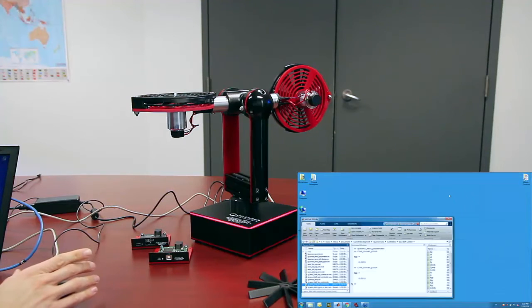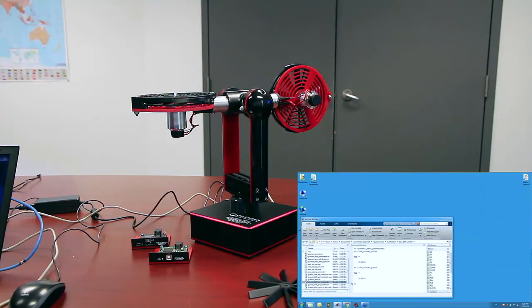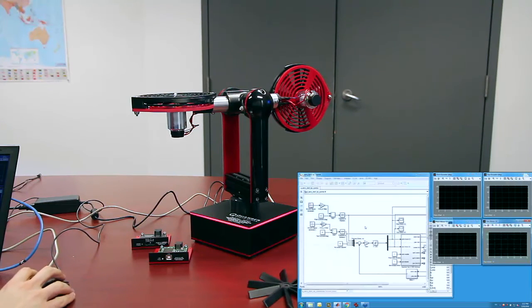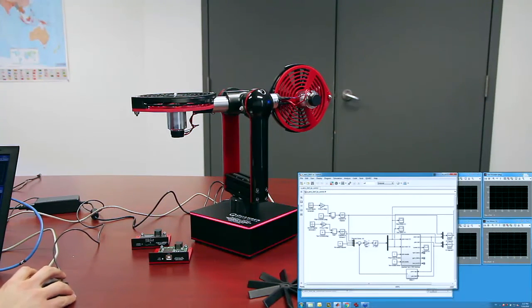And note as well, when I'm running the controller, the LED light was changing as well. So now let me show you a different approach. This is using a state feedback controller, which is a coupled design. So the model that was based on deriving the gain, which we were using the linear quadratic regulator method, or LQR, was based on a model that does have this coupling effect. It takes that into account.